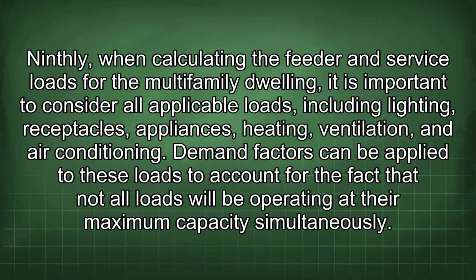Ninthly, when calculating the feeder and service loads for the multifamily dwelling, it is important to consider all applicable loads, including lighting, receptacles, appliances, heating, ventilation, and air conditioning. Demand factors can be applied to these loads to account for the fact that not all loads will be operating at their maximum capacity simultaneously.